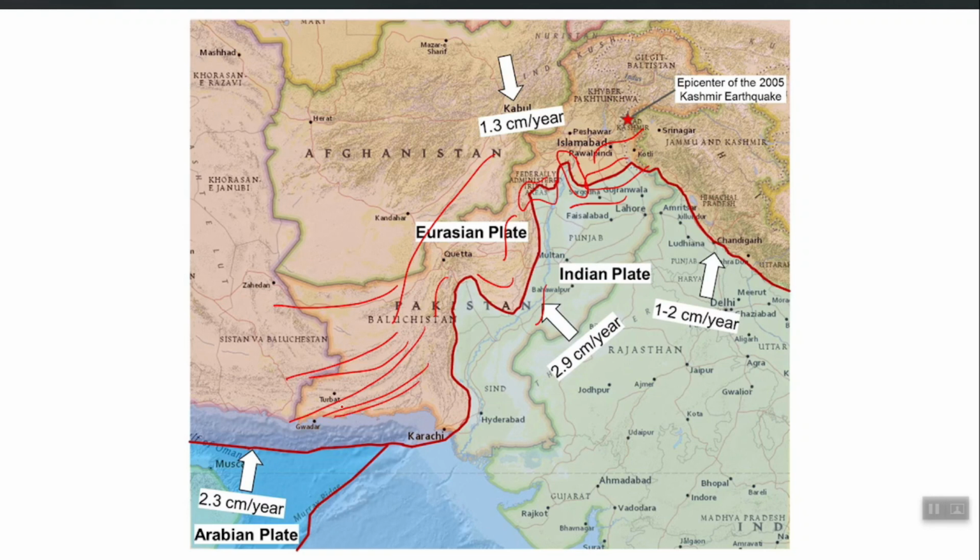So along the main plate boundary, we also have other fractures in the land. Fault is a general word which can be used for any fracture, and it can also be used for a segment of the main plate boundary. For example, we say MBT in Islamabad, the Main Boundary Thrust. It is one seismic source which mostly governs the seismicity of Islamabad and its surroundings. Its name, Main Boundary Thrust, indicates that it is part of the main convergent plate boundary, a thrust fault.